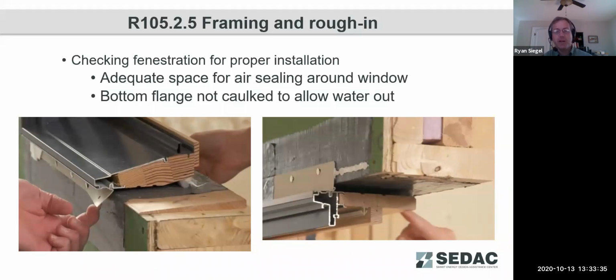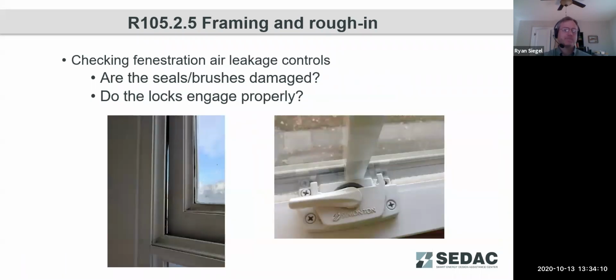Something else that this chamber does provide for is that, because this chamber is going to be at a very similar air pressure to the outside, this water seal has very little air pressure across it. So there's going to be much less chance, due to lower driving force, of water penetrating that seal. Again, that interior seal we need to make sure is continuous on all four sides. The exterior is going to be continuous on three sides, top and the two sides.